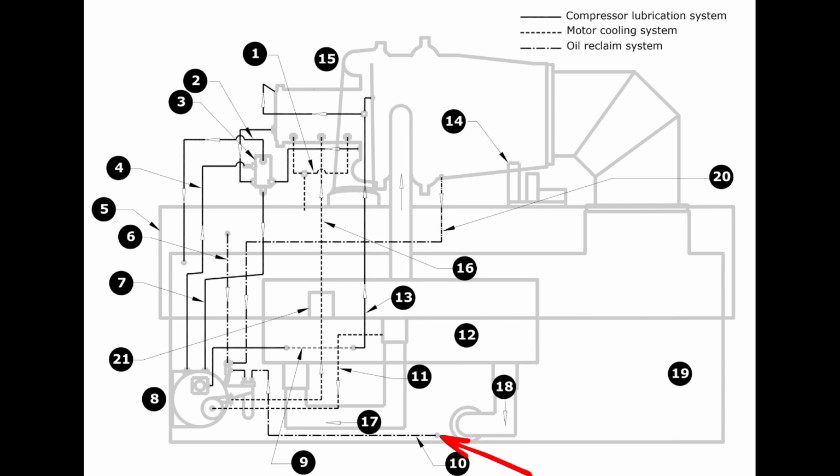When you read the specifications in the manual, these are not meant to be just full open. What you could end up doing is sending too much liquid refrigerant through this line to the eductor, and we cannot properly convert that to the vapor that we need from the hot gas process. When we overload our eductor, we run the risk of sending liquid into our tank, which is not a good thing.